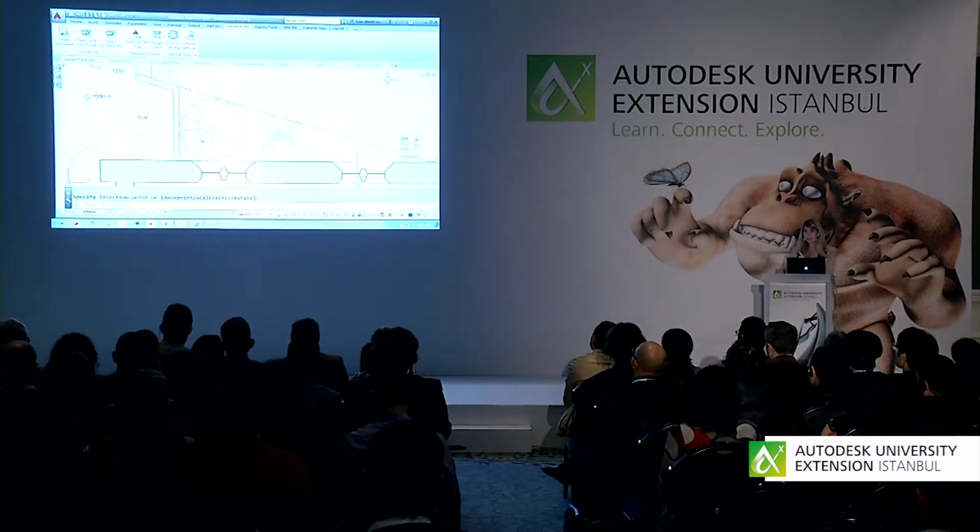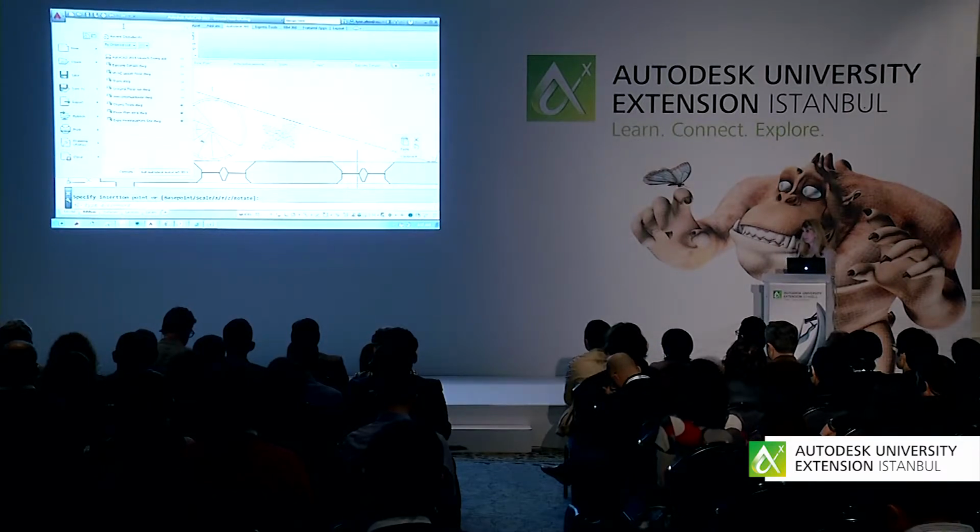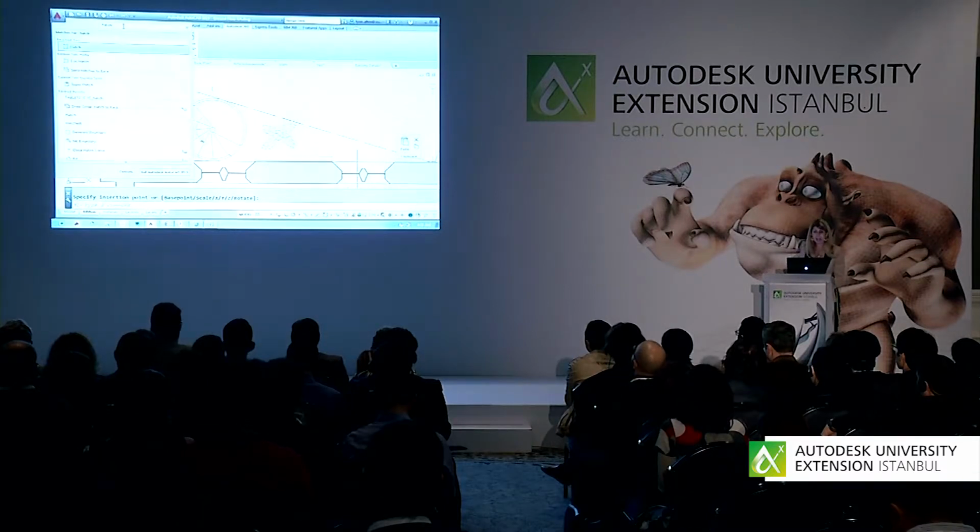If you're not on AutoCAD 2015 and you're making the move to the ribbon, you can also click on the big A in the upper left-hand corner, the application menu, and you can type in your commands here. So I could type in, for example, the hatch command, and it would show me exactly where it is in the ribbon, for those of you who are not in 2015.